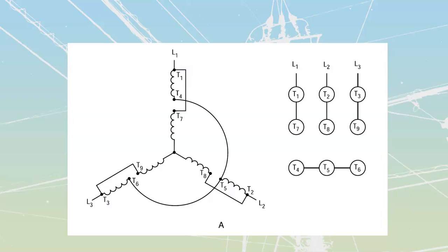You're going to find that information off the nameplate, by the way. If we take a look at these ones over here, what we see first is that we have a lower voltage 9-lead motor connection. The first one that they show us over here is the low voltage Y. What you'll note is that this is just going to be a parallel Y.